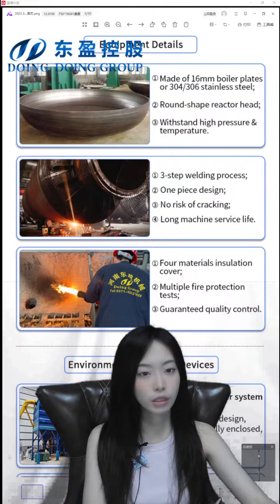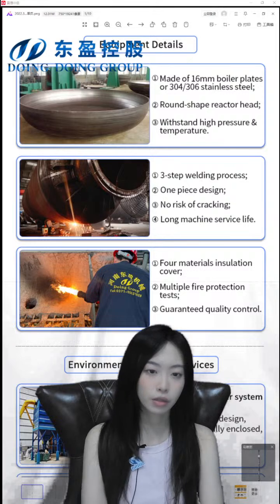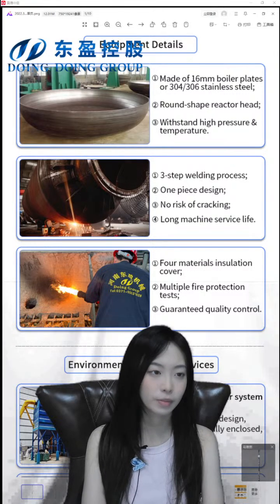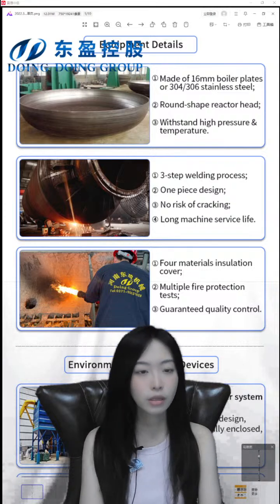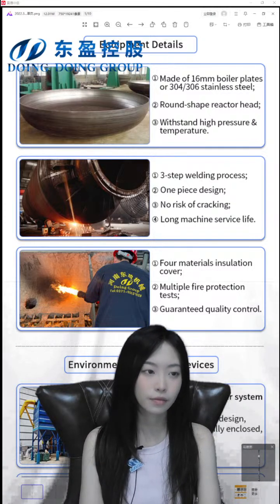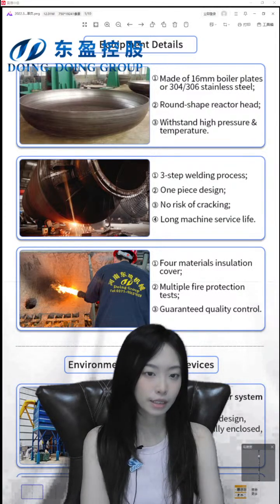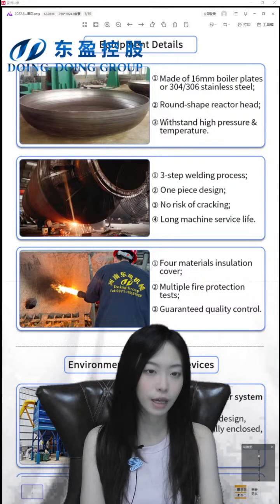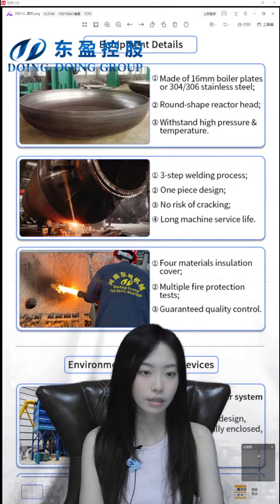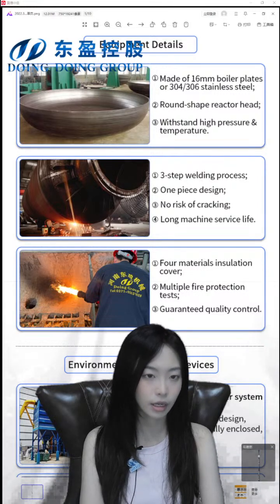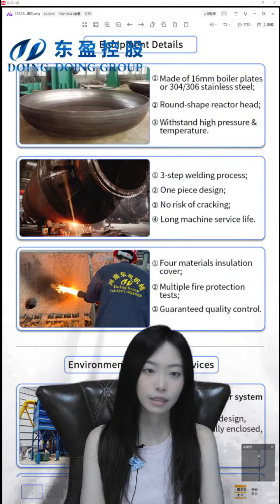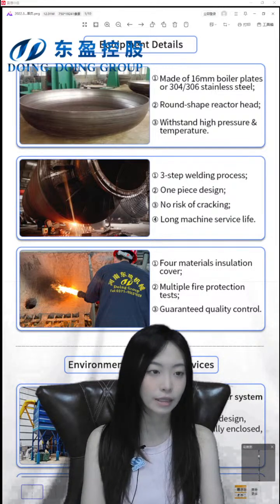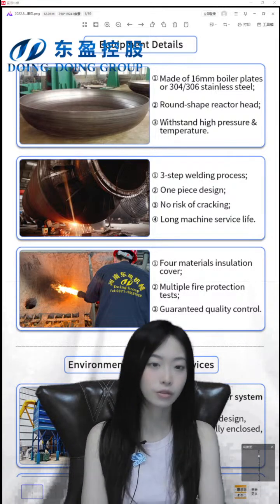About this, if your raw material is waste plastic, the raw material is random, and it's not as certain as with whole tires. With tires, we know there is steel wire and rubber in it, but with plastic we are not sure whether it is PP, PE or PS, so the oil yield is not quite sure.